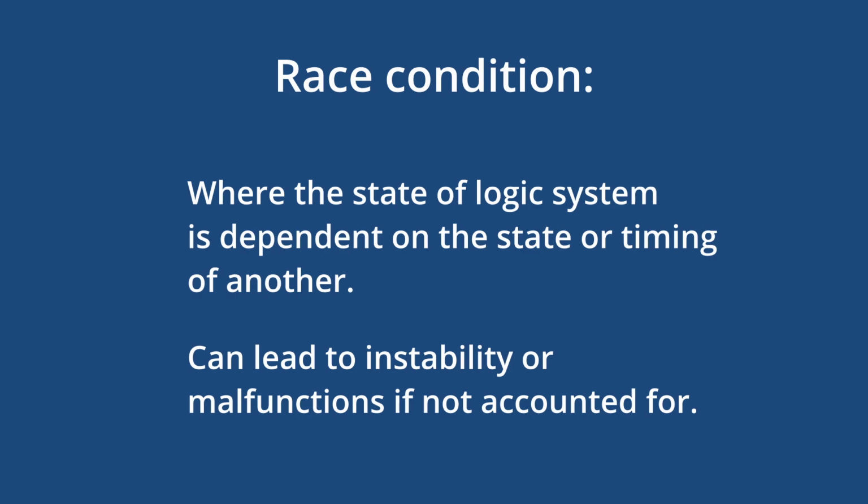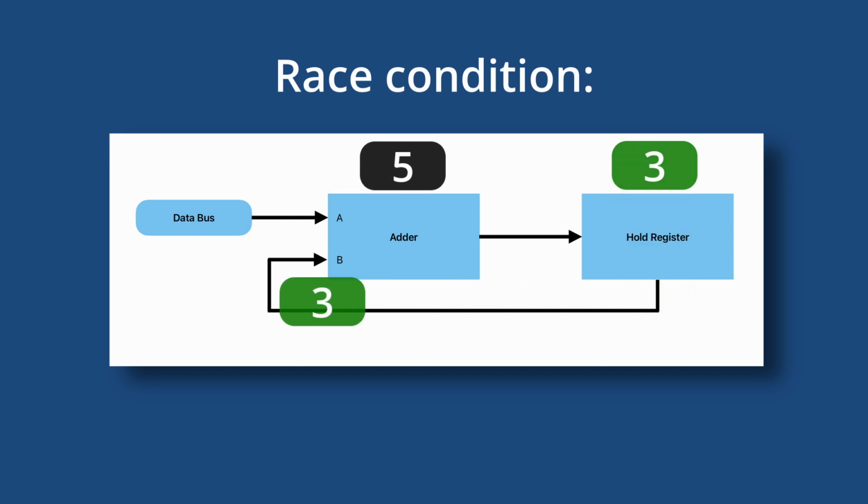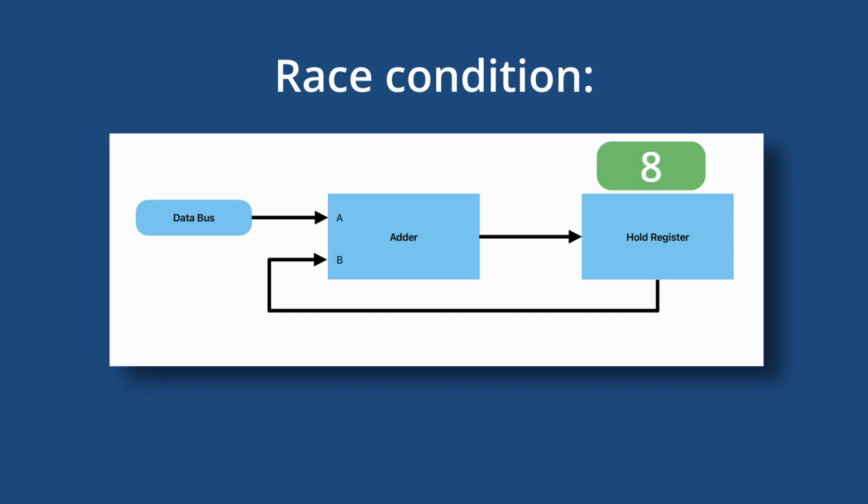If we have everything operate on a single clock signal, we'll run into issues where the registers or the RAM latch in data, possibly before that data is ready to be latched. For example, imagine if we want to add the value 5 into whatever value is currently in the ALU hold register. Well, the action of adding 5 means that the value 5 travels through the data bus into the input gates of the ALU. It then passes through the adder circuits, and then that value is presented to the ALU hold register. Those actions don't happen instantly, even in the simulator.